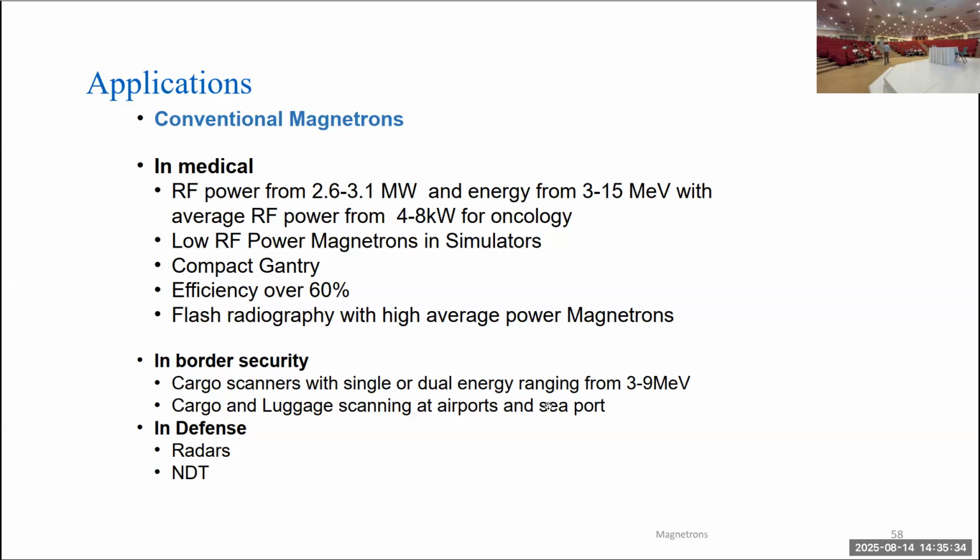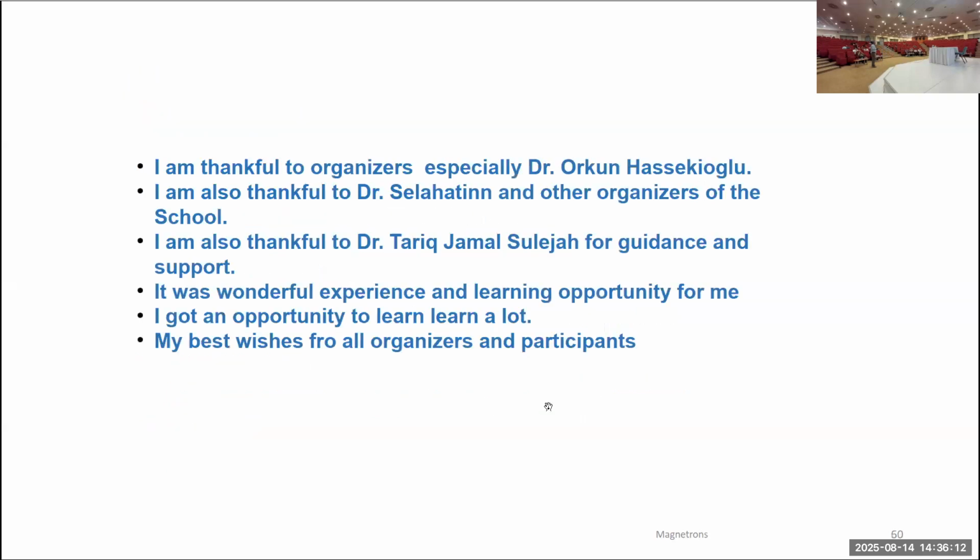No, the frequency of a resonator depends upon its size. If it is slightly heated, its frequency is changed. The change in frequency per degree is almost 5 kilohertz. If you change the temperature of a cavity by 10 degrees, almost 50 kilohertz change in frequency will occur, because the size is changing. Size is changing due to expansion and contraction.